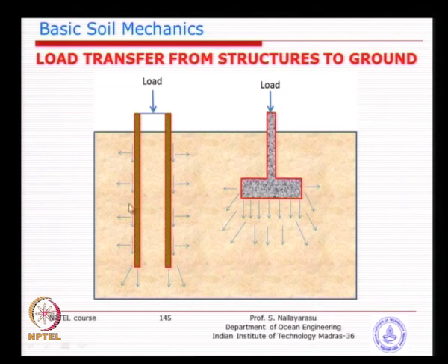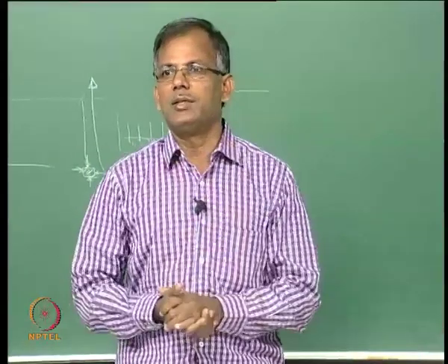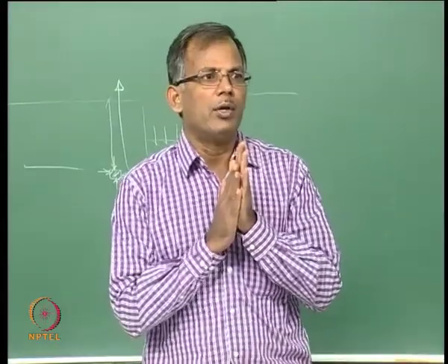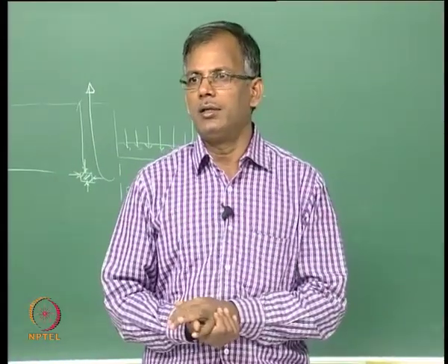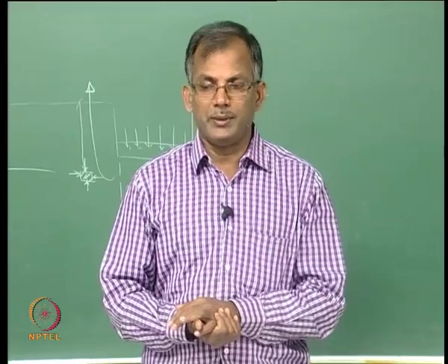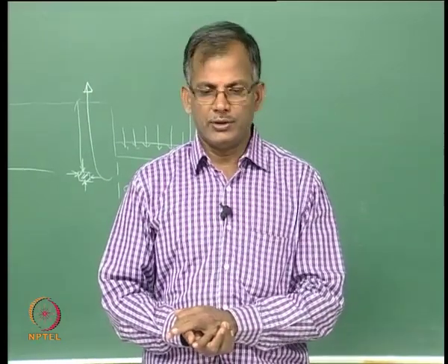So you can see here, if it is a C-phi soil with sand and clay, you will see that a mixed pattern of the soil pressure distribution will take place. Whereas in the case of pile foundation, predominantly we are trying to fail the soil by shear along the surface between the soil and the foundation material. And of course, when it is being done, the soil on the side is getting squeezed away because the pile is getting inserted. So whatever the friction that it has to overcome, during the same time the soil is actually getting lateral pressure, which needs to be taken into account when we are doing the foundation capacity.